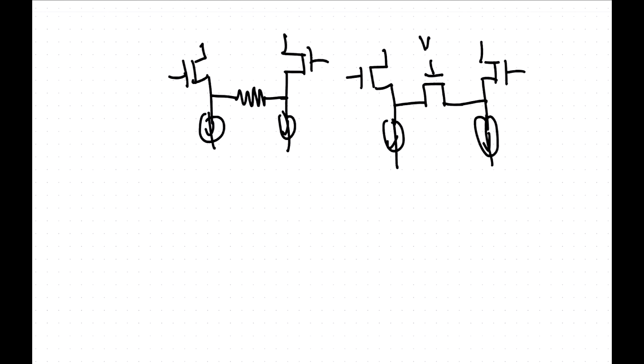Now, if you have a circuit where you apply a fully differential voltage at the input as you control a common mode, then this is actually a linear circuit if it's in the triode region and strong inversion. As long as V isn't too big to get into saturation.